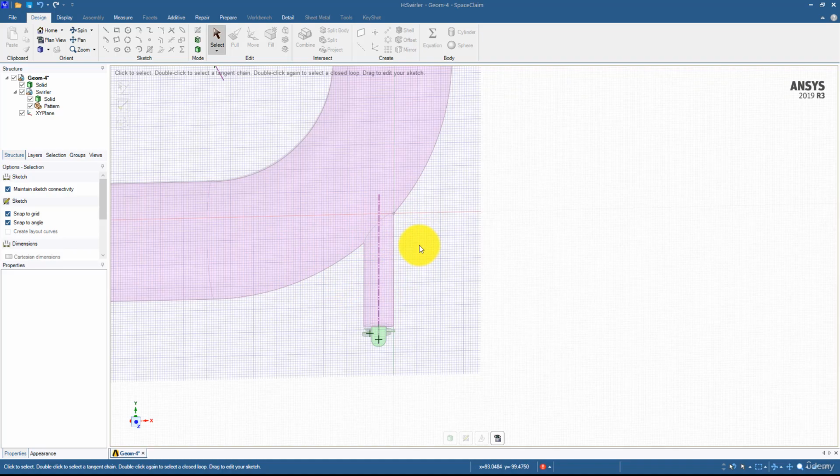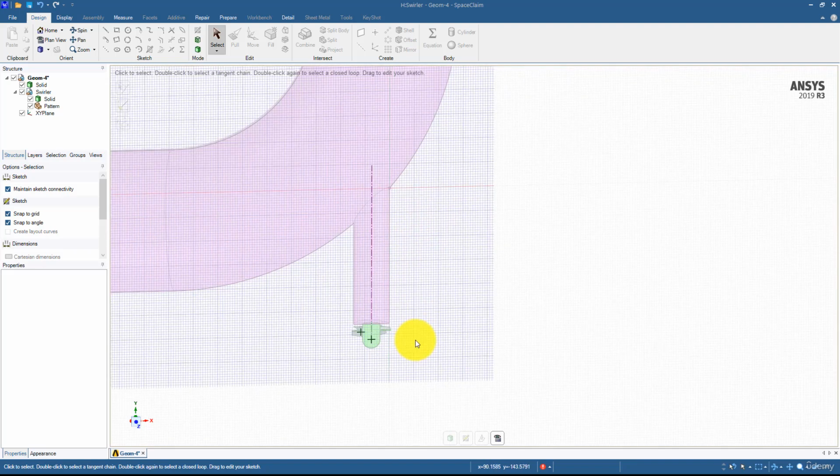Fluent will not give you more work, because the only change is the meshing and the geometry, which is subsequently from the geometry to the mesh, and all other things will be the same. And the same goes with the CFD-Post. Everything is already done in the CFD-Post. You have to just change the geometry a little bit, update the mesh, run in Fluent, and then update inside the CFD-Post. You can get the data on how, if I place this Swirler at different heights, it is going to affect my mixing process.